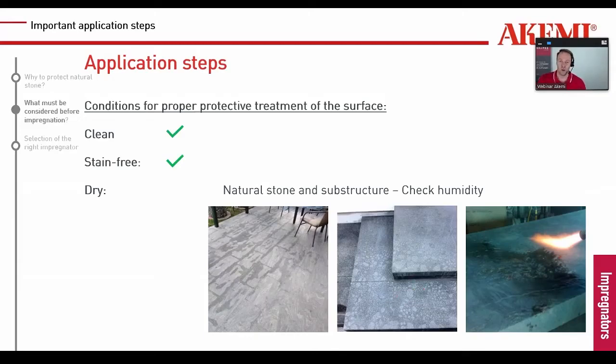A third thing is humidity, especially in these times when you're in the northern hemisphere, where we have winter time. When you bring in stones which are stocked outside into your workshop, usually you have a temperature change to maybe 20-25 degrees, and they start to sweat, and they get a lot of condensation water. Outside they look dry, and when you bring them inside, they look dry too, but then they start to sweat. So here you have to be aware, and you have to dry the stones. I will show that to you right away.